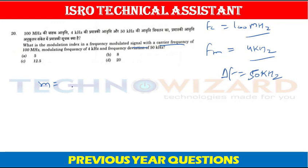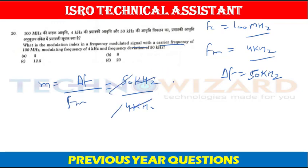Modulation index in a frequency modulated signal is given as frequency deviation upon the modulating frequency, that is FM. Del F is given as 50 kHz upon FM is 4 kHz. This will get cancelled by this. 50 divided by 4 is 12.5 is the modulation index. Therefore, option C is the correct answer.